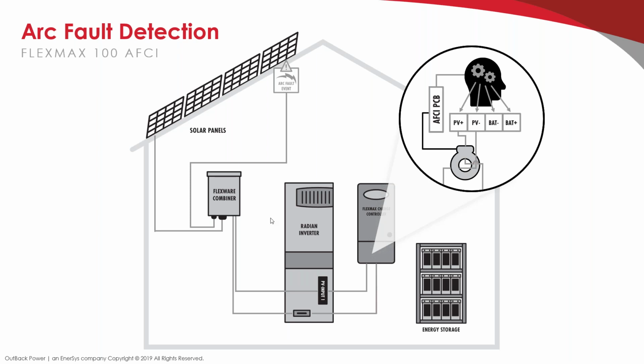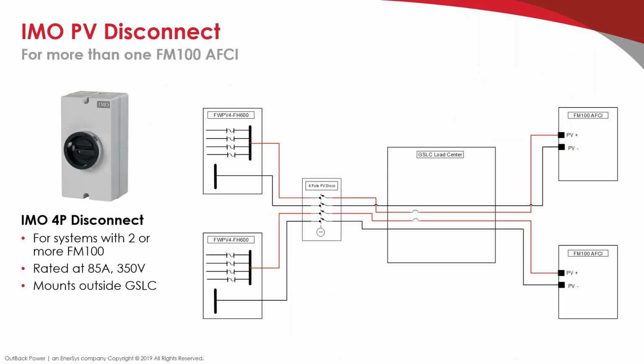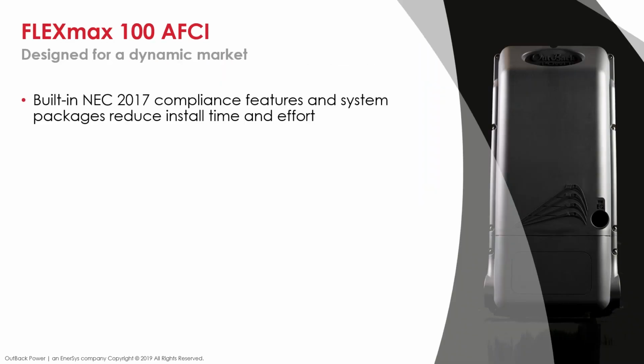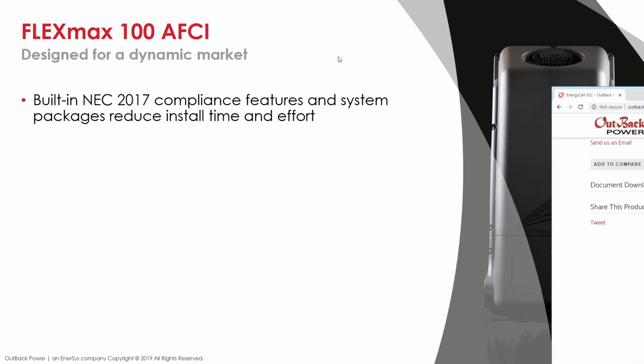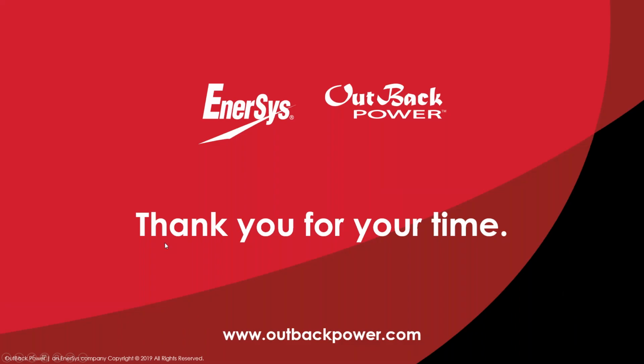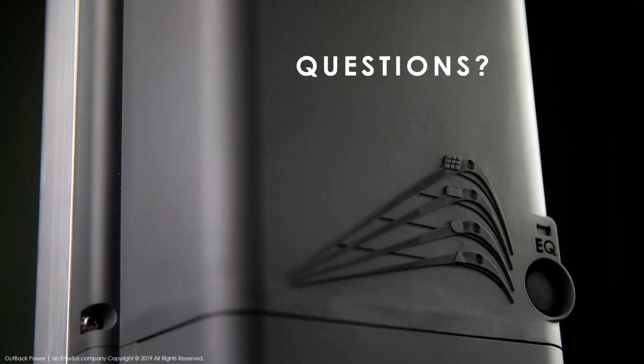Last question here is, are the XLC batteries lead acid? Yes, they are. They are a sort of modular AGM battery. I don't have an image of them, but they are online now. They're on our website, and this is what they look like. So this is the XLC battery. It comes all in a single enclosure with AGM batteries. And look at that, it's 3,800 cycles at 50% depth of discharge, 17-year standby life, pretty awesome. Their specs are along the lines of a lithium-ion battery. It's pretty impressive engineering on these batteries, and a full 10-year replacement warranty. So that goes back to the 10-year System Edge warranty that we showed before, which we're all pretty excited about being able to offer.